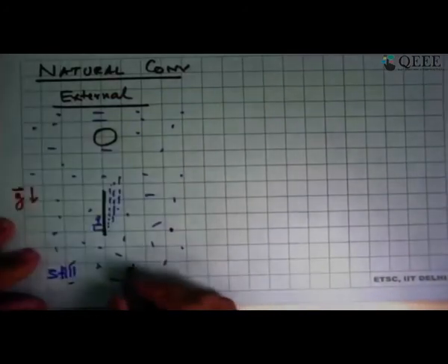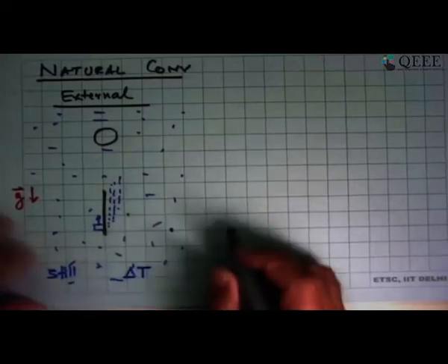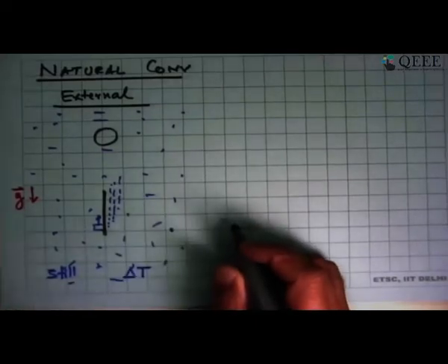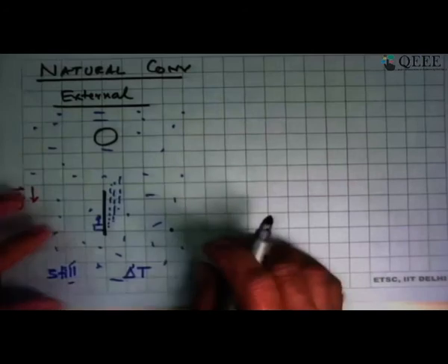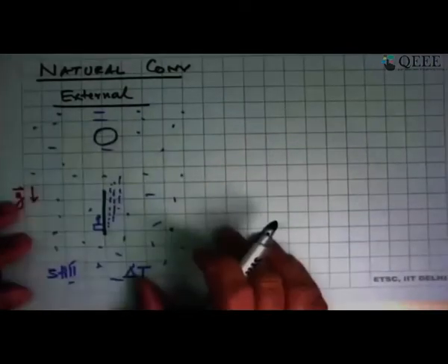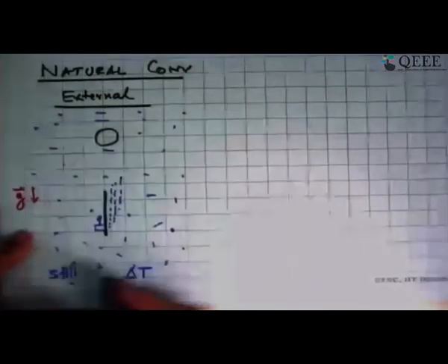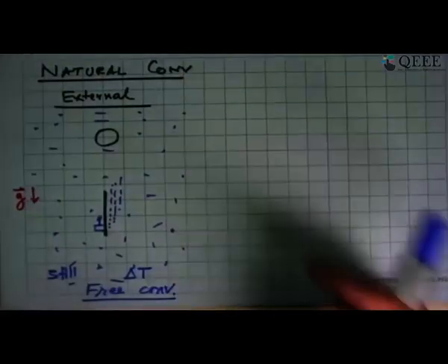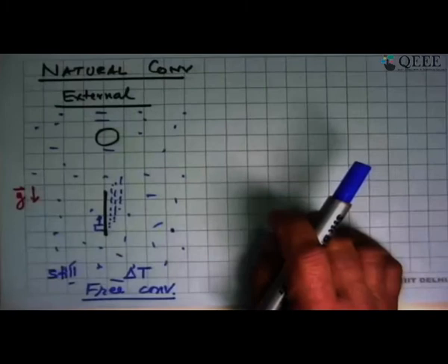What this means is that this flow took place because the temperature gradient was forced on the fluid and there was a body force field in there. This thing where temperature difference induces a flow is called natural convection. What I've shown here is a particular class of natural convection where there is a heated object sitting in still air where there are no other surfaces on any side. This is termed free convection, and there are just as many problems that we see in the real world where free convection actually takes place and we have to really worry about it.